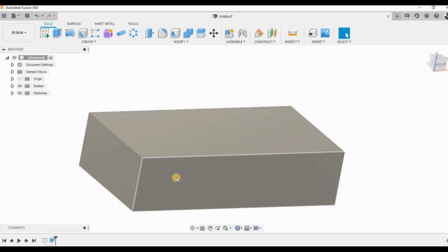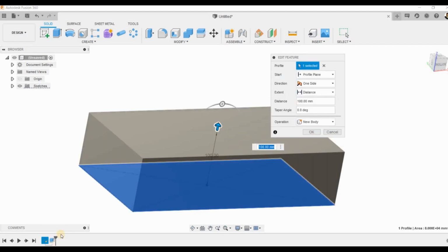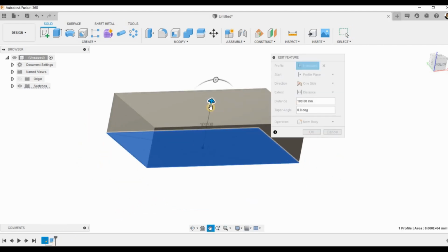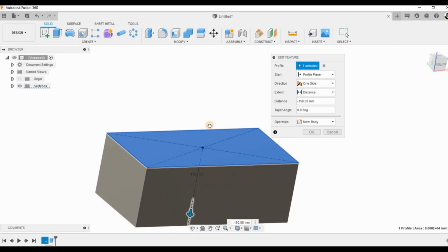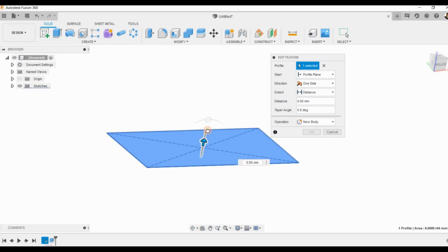And the next one is the extrude. So if I have to edit this extrude, I can double click here. And I will again get the same dialog box. Instead of extrude, now I'm going to get it as edit feature. And this feature I can edit from this dialog box or again like how we have seen from the workspace.